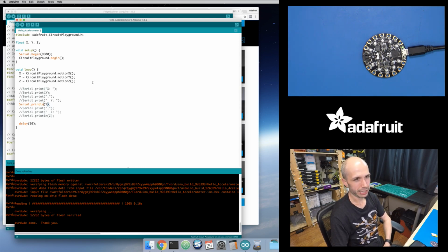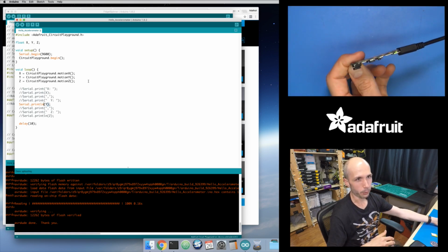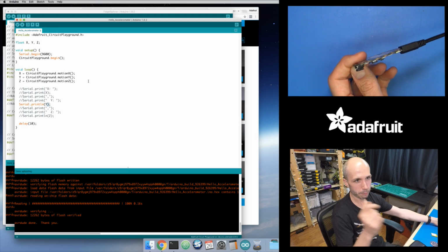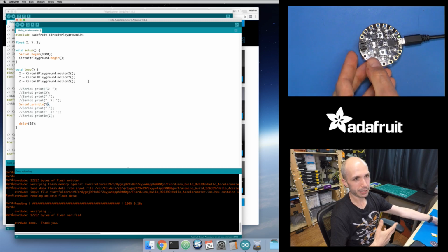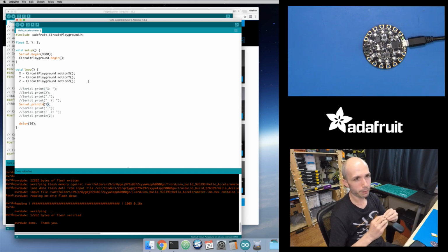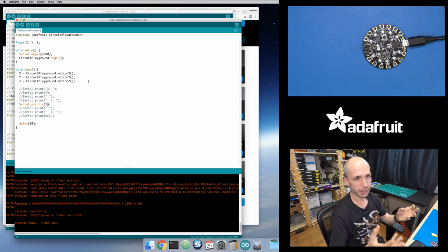I just intuitively started thinking about this, and my general thought is, okay, I want to define what is a steady state for the accelerometer value. When it's held in this orientation, it's going to settle down to some steady state. If I hold it like this, that steady state might change, just based on the force of gravity. But I want to figure out what that steady state is and be able to update that dynamically as the board moves around. And then I want to find any time an acceleration value comes in that's orders of magnitude different from that steady state, either positive or negative, then I could consider that a peak.